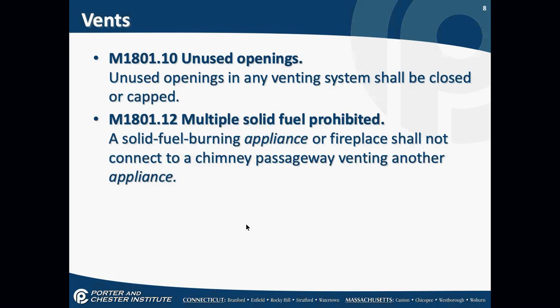Okay? A solid fuel burning appliance or a fireplace should not connect to the same chimney as another appliance. In other words, if we have a wood fireplace on the first floor and a wood fireplace in the basement, you cannot connect them to the same chimney passageway. Again, if you look down from the top of a chimney, there can be multiple passageways. It might be one chimney, but they cannot be connected to the same passageway. By the way, I can't connect oil and gas appliances to the same chimney passageway either, or the same vent pipe.